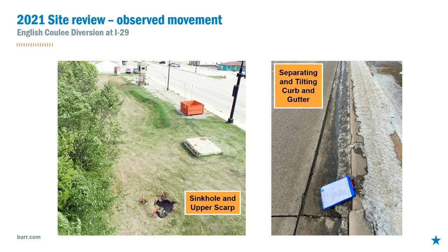As we're monitoring the slide over time, we're starting to notice some impacts to our infrastructure. Initially, everything seems to be north of the road, not having a ton of impacts on us. We're just keeping an eye on it, but some things start to show up. There's a storm sewer pipe that's outletting into the river. That starts separating significantly, and it's causing a sinkhole. The slide has pulled that pipe apart, and material is getting in there and washing out.